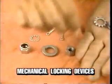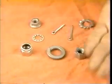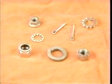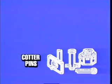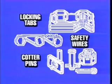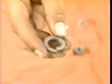Mechanical locking devices prevent the nut or bolt from coming loose. These devices help in areas where varying loads and vibration are common. Cotter pins, locking tabs, and safety wire keep nuts and bolts from coming loose by preventing them from turning.